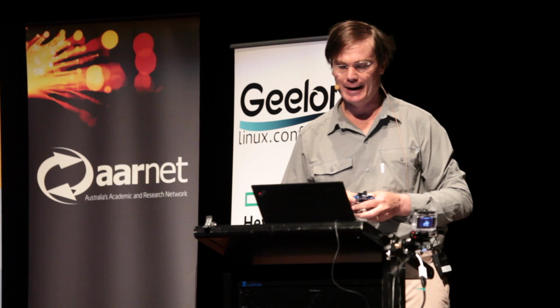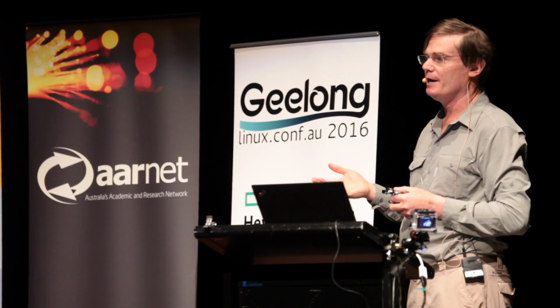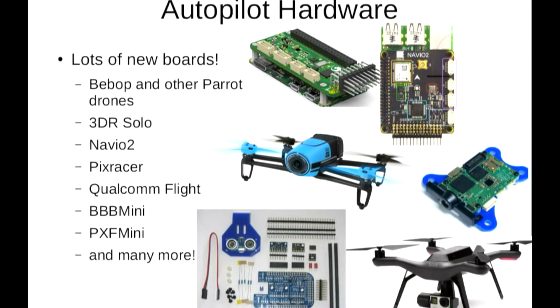If you want the pure open hardware, open software experience, then the one on the bottom left, the BBB Mini, is for you, which is a kit for the BeagleBone Black, a do-it-yourself kit for amazingly low money that provides a fantastically capable autopilot on top of the BeagleBone Black, utilising the programmable real-time units, the PRUs, for doing all the necessary real-time stuff.